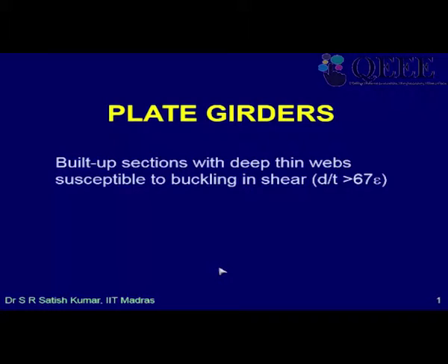Now, why would somebody do something like this? It is simple. When you have a large bending moment, or when your beam design is governed by deflection, I need a large moment of inertia, right? Even for a large bending moment, the farther I put the flanges, the less area of flange I will need.